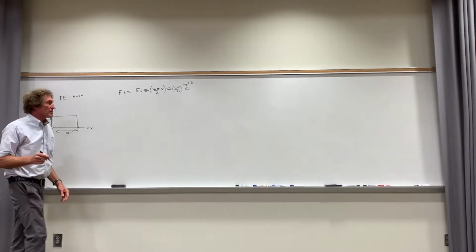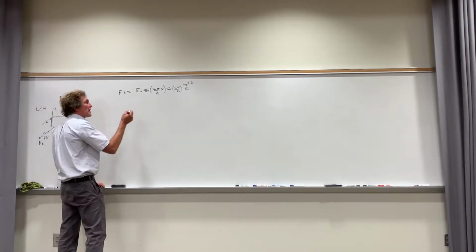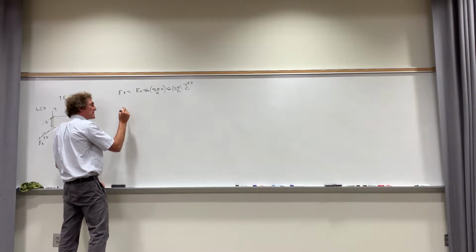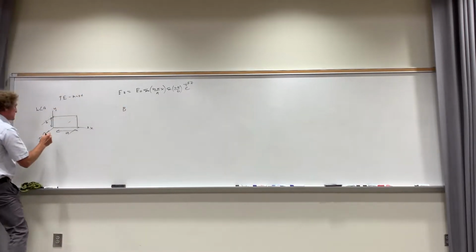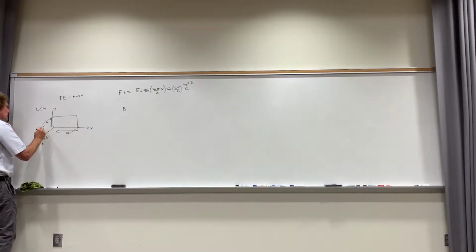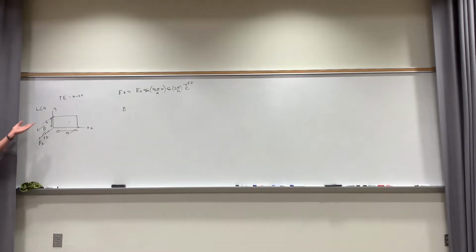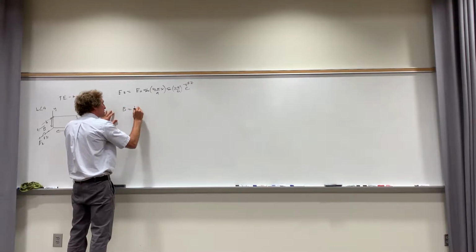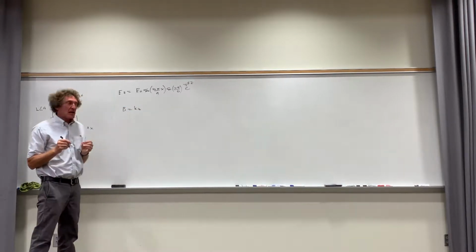From there, a few other things that I mentioned before that we found out when we did separation of variables, we came out to this, that the actual beta in the guide, that beta has to do with the actual beta that's associated with the flow of power in the Z direction. Do you follow me on this? Normally they call that k sub z. Dr. Wentworth just puts it as beta. I like to put this here as k sub z. So it's the wave number in the Z direction.